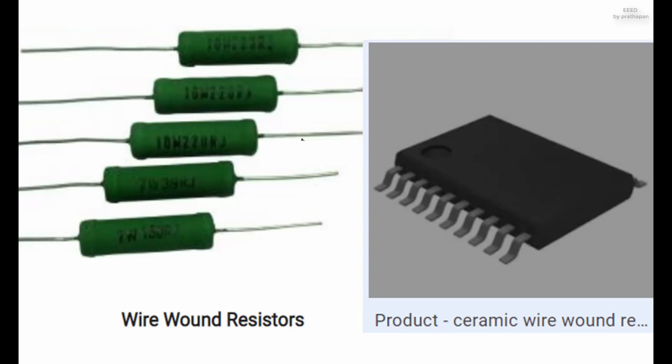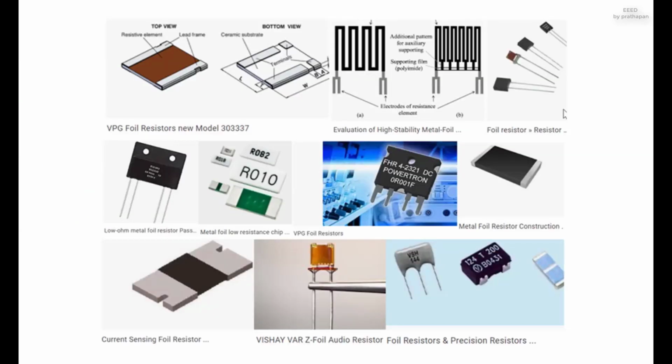Metal foil resistor. In 1960, Felix Zandman and Sidney J. Stein presented a development of resistor film of very high stability. The primary resistance element of a foil resistor is a chromium-nickel alloy foil several micrometers thick. Chromium-nickel alloys are characterized by having a large electrical resistance, about 58 times that of copper, a small temperature coefficient and high resistance to oxidation.